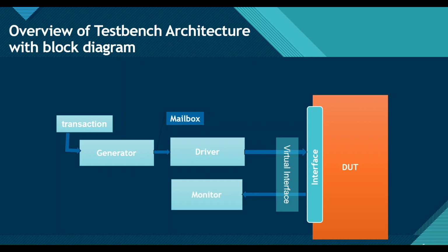Next, the monitor. The monitor is also a class. It reads the output from the DUT using the virtual interface, creates a transaction object, fills it with the observed output values, and sends that transaction class to the scoreboard using the mailbox.